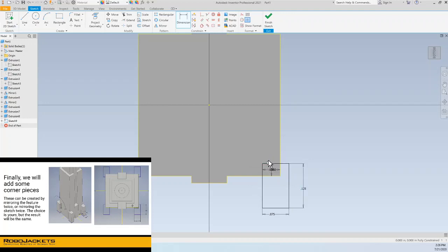Now if I had drawn the rectangle in this space over here, these dimensions wouldn't have worked, because I have to have at least some correct. So if I had made this dimension between these 2 lines 0.035, it would be 0.035 in this direction, which is not what I want. I don't believe you can do negative distances. It's better to create the shape in the correct place to begin with, and then specify from there.